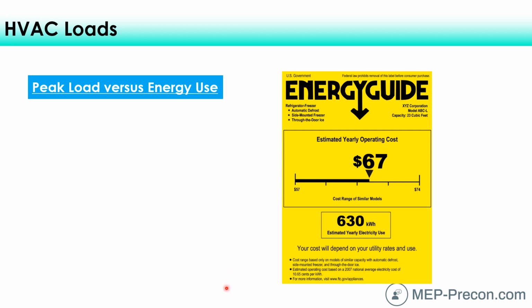So in energy analysis, no matter what your peak load is throughout the year, that happens at an instantaneous time, maybe for a couple minutes or something. Everything else in the year, you're going to be off that peak load. For example, a cooling load peak might peak out at, say, August 15th at 4 o'clock in the afternoon when you have a ton of people in the space and they're using computers and all the lights are on. That would be the very worst case peak load. That would be what your equipment is sized for.